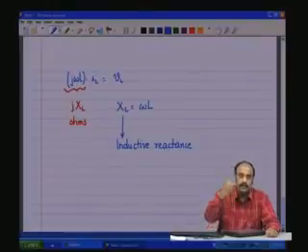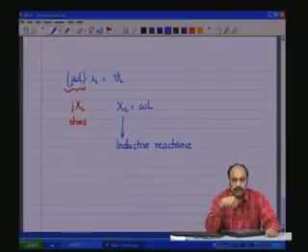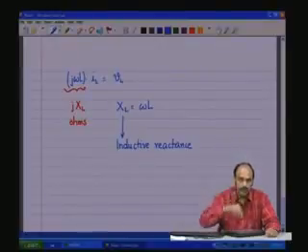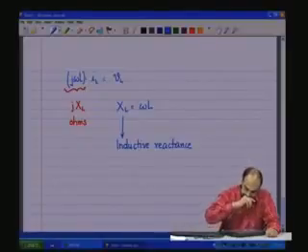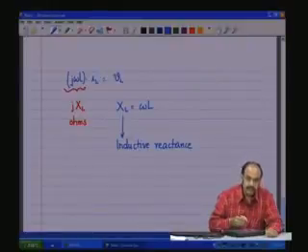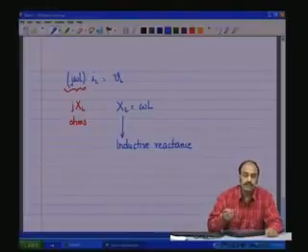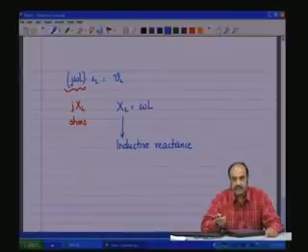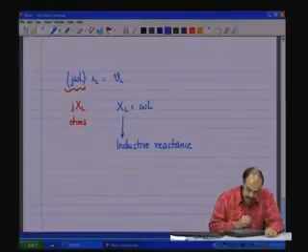If you have a pole on the left at the top, you will have a corresponding mirrored pole on the left at the bottom, and there is a 180 degrees phase difference between these two, to indicate that there is a resonance action. An oscillation can only occur if there are two different types of energy storing elements, one which is kinetic based and the other which is potential based. Anyway, coming back to the equation here,